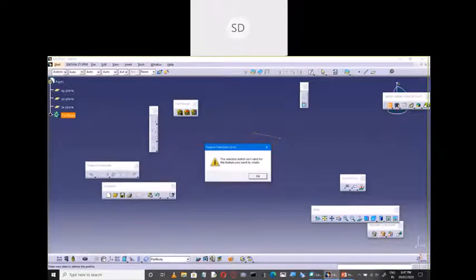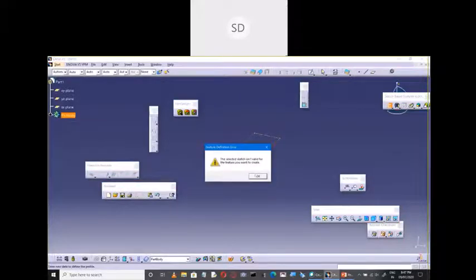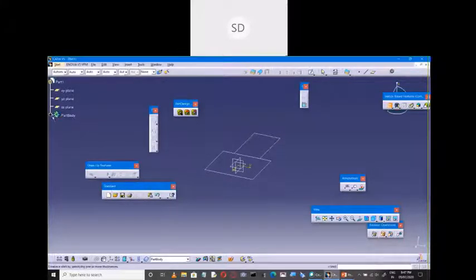So validate the feature you want to create, because it is going to create intersected portions here. Intersected portions. It has to create a loop in such a way that it has to form a complete loop. It means complete close. Now this line is acting as an intersected portion for this surface as well as this surface also. Let us go for editing sketch.